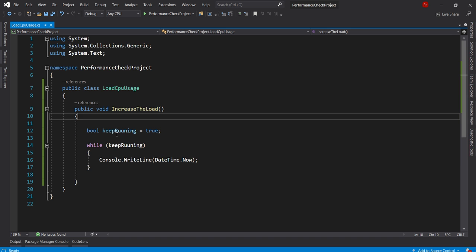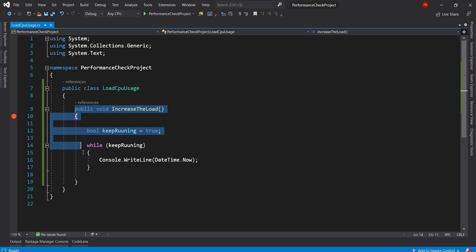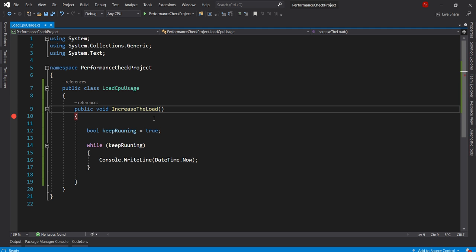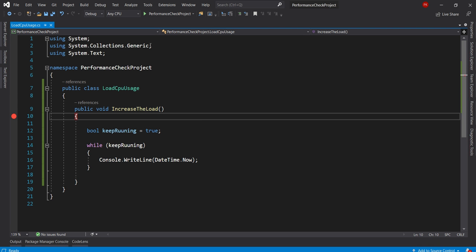To check and collect the CPU data, make sure you are setting your breakpoints. If I want to test this particular function, I have to put my breakpoints over here, and then finally I can see how much time it is taking, right? So let's say execute.